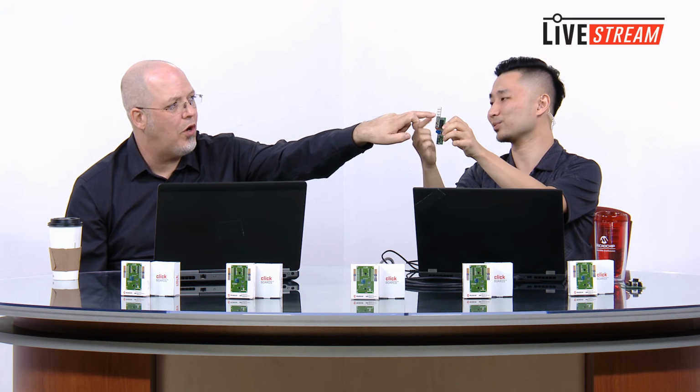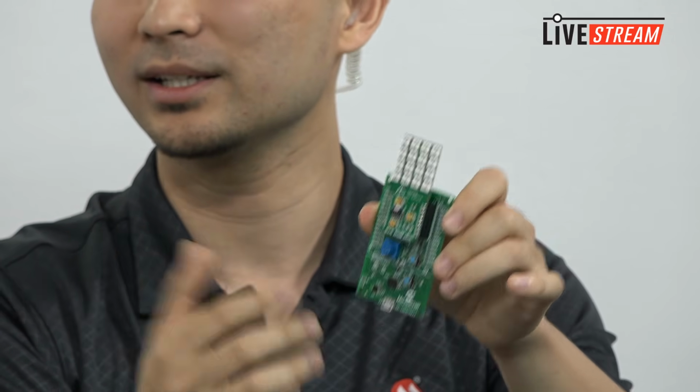So you can. Basically, the LEDs are implemented as a string. In your data, you're always sending data for all of your 16 LEDs together. If you want to get to a particular LED, you have to shift through all the other LEDs, but you can just send empty commands so you can light up just one of the LEDs in the middle. If you just want to light up the first LED, it's just 24 bits of data. But if it's 5 LEDs in, you have to shift through 4. Yes, exactly.